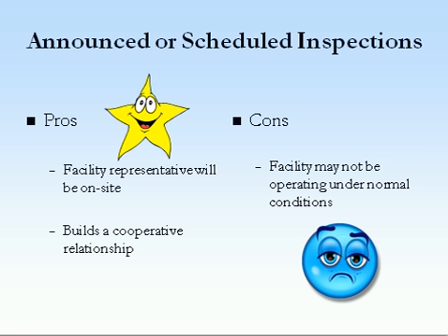One thing that you can also probably do when you are scheduling inspections, you may be noticing that different industrial processes are run on certain days of the week, and then you can figure out when you need to come out in order to make a thorough inspection.